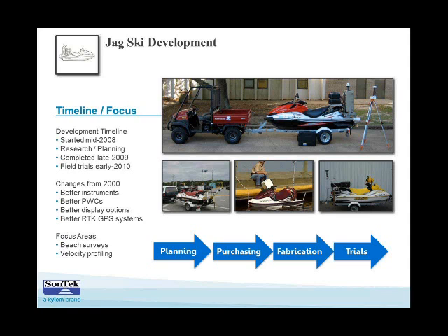Next bullet. Make your navigation corridors generous. I started off thinking, well, I can make them pretty narrow. I'm a pretty competent navigator, and I realized that it's not only me, it's the conditions at the site and the people that are in your way. So it's nice to make the navigation corridors in the HydroSurveyor software as big as possible so you can keep your track reference. And then go ahead and just throw up the last 1 or 2 bullets.